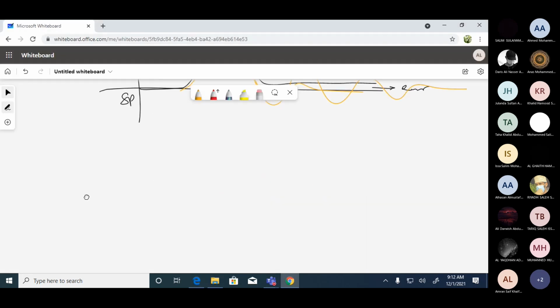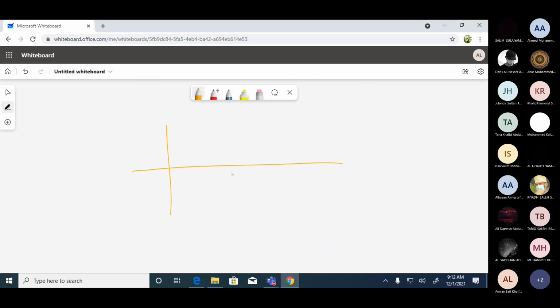Let us say, okay, there is a disturbance because of which the controller output is producing an output. This is because of the integral output, okay, integral controller. Then it is going to reduce, increase, like this, and then it is going to stabilize. This is the output from proportional and integral together. So here you see there is too much time taken. Plus, in the first, there is something that is called overshoot. Overshoot means the value of the process variable is going way above the set point.